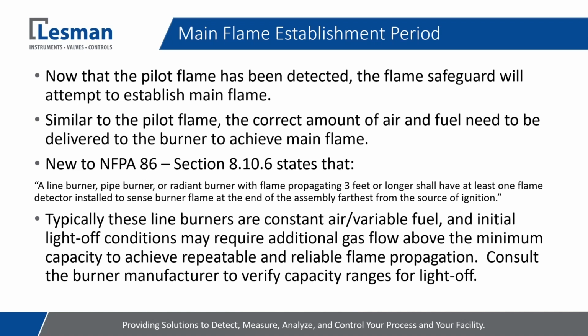But after you get to that pilot flame establishment period, now you're going into the main flame establishment period. And really, when I'm on a startup and I get through that pilot flame establishment period, I feel like I'm in the home stretch, right? I've verified that flame is occurring, that my flame safeguard is detecting the flame, but you could still get caught up in this main flame establishment period.